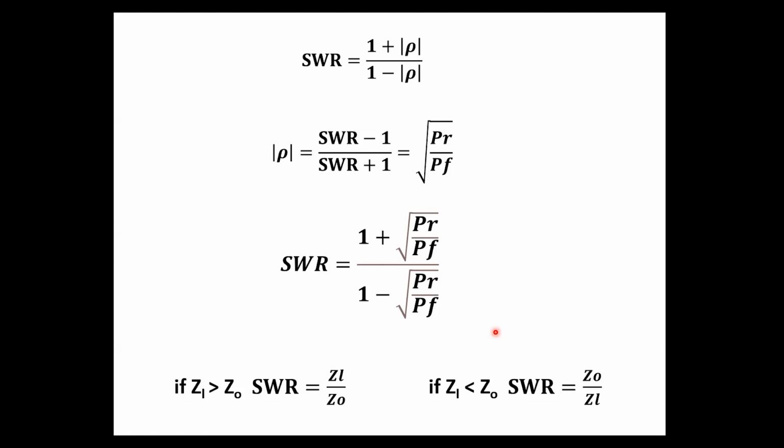Then using my Smith chart or some of these software programs, and I'll show you again at another time, some of these software programs will eliminate the coax or the feed line, whatever it is, between the radio and the antenna. It's just going to do it mathematically and calculate exactly what that SWR is at the antenna. So here I can calculate the impedance at that point.